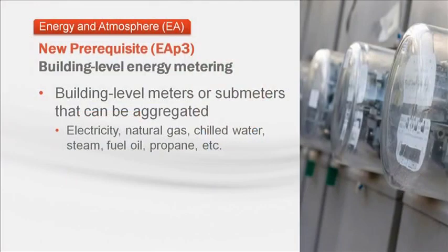Now, in addition to the 3 options we just covered, building type specific requirements for retail and data centers are allowed. More information is in the handout available from your site coordinator. Now, as mentioned earlier, there's a new prerequisite to meter building energy use by type. Either building or aggregated submetering is required for all the energy uses in the building. Depending on the energy sources, this may be a significant increase in metering. And remember, this is a prerequisite.